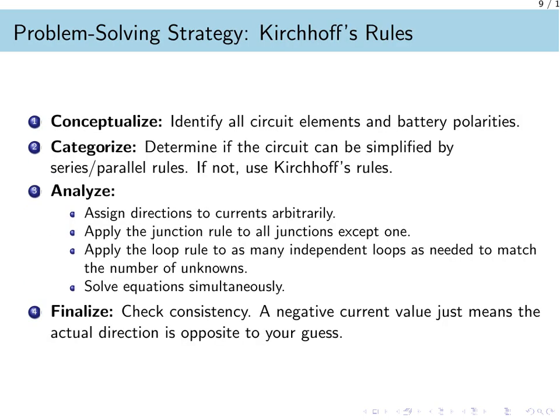When tackling these problems, follow this four-step strategy. First, conceptualize. Identify all circuit elements and the polarities of the batteries. Second, categorize. Check if you can use simple series or parallel rules. If not, proceed with Kirchhoff's rules.